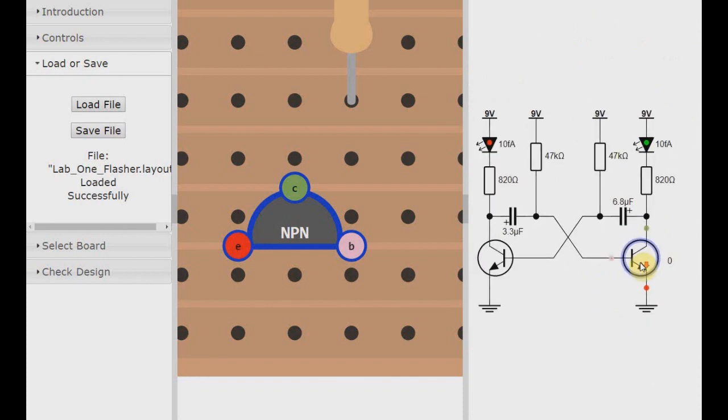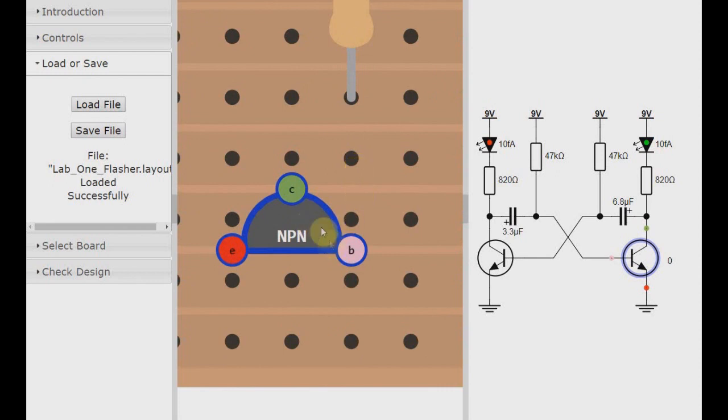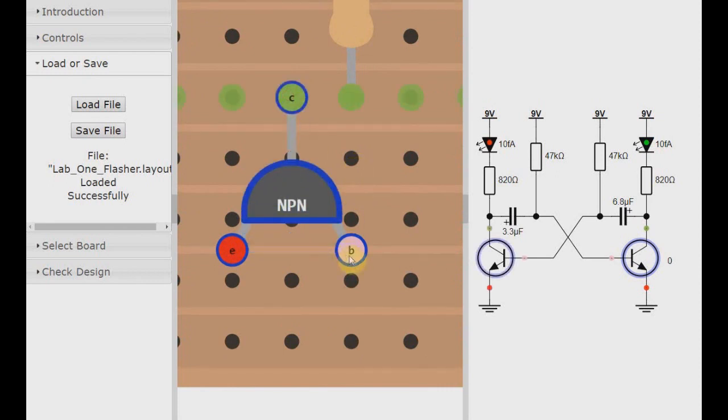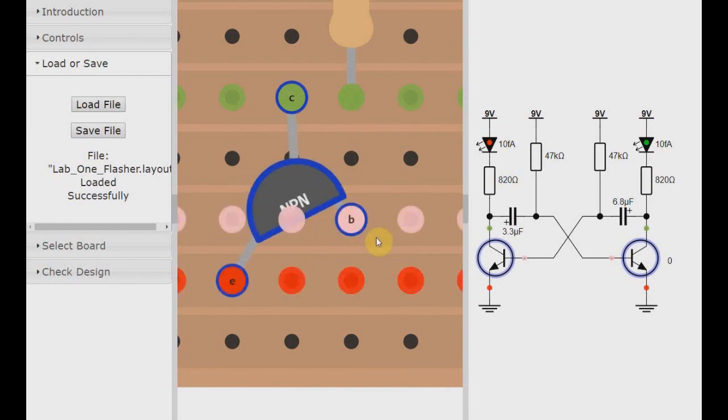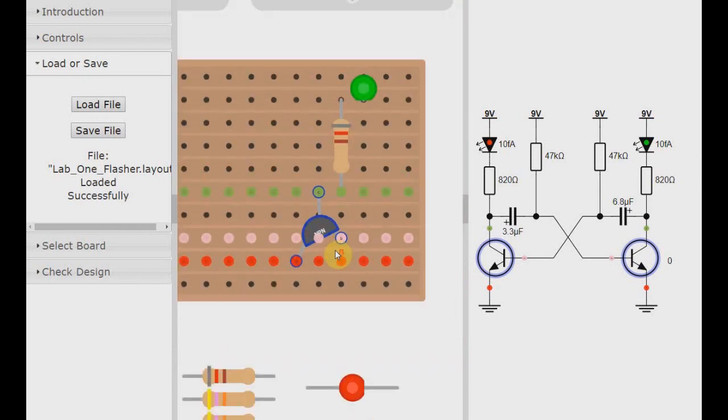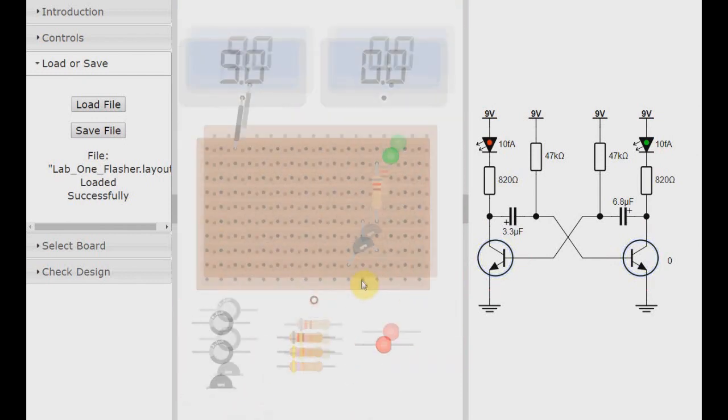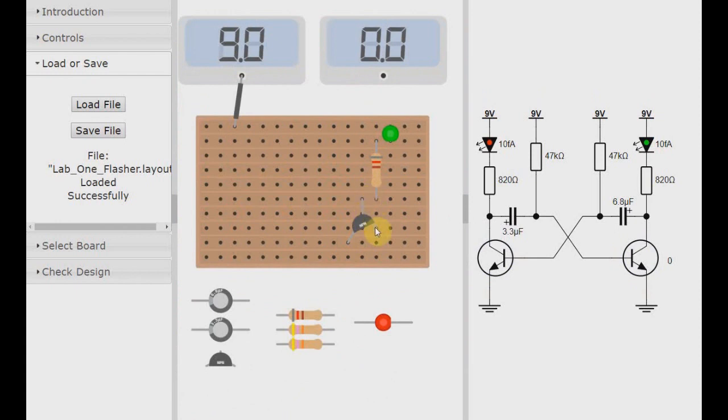And we've got to get the transistor wired up the right way round. Now, the collector here is what needs to be connected to this pin of this 820 ohm resistor. So I could put the collector there, and say the emitter there, and the base there. It's not a brilliant design, because if you look at the actual physical shape of a transistor, in order to fit it into the circuit board like that, you couldn't mount it very closely to the board. But it would work. Electrically, it has the connections that you need.